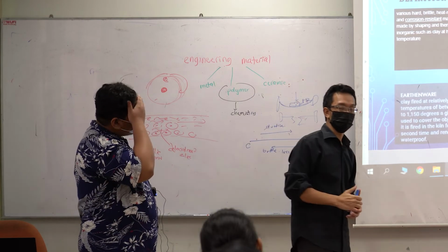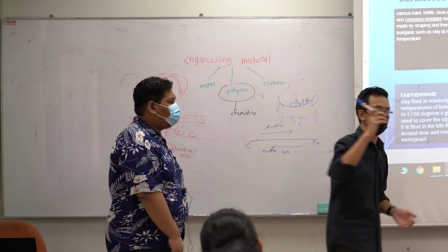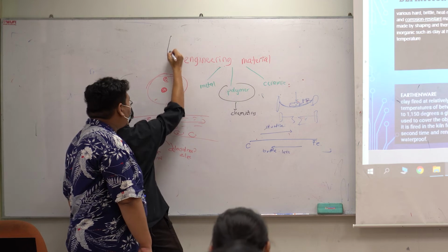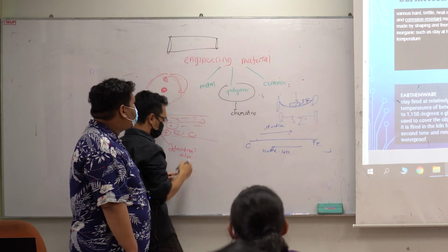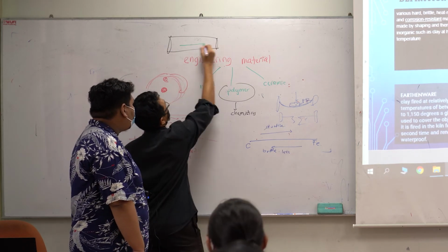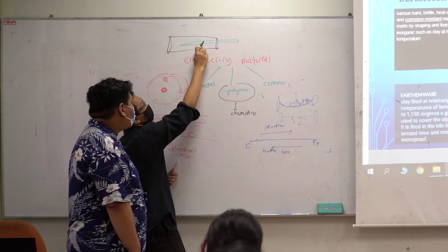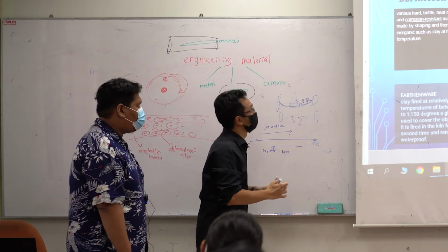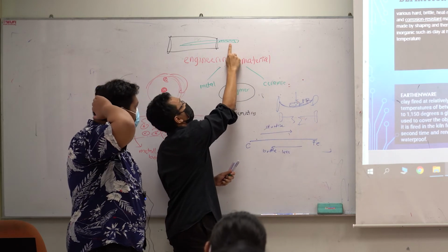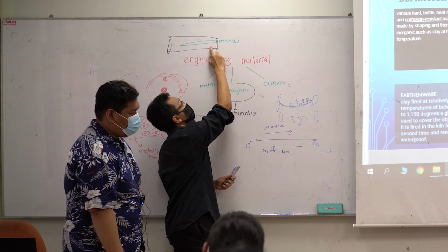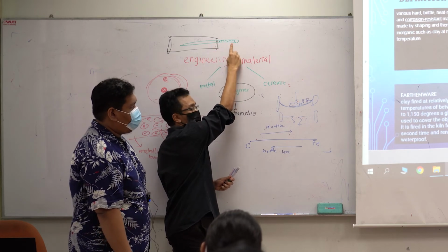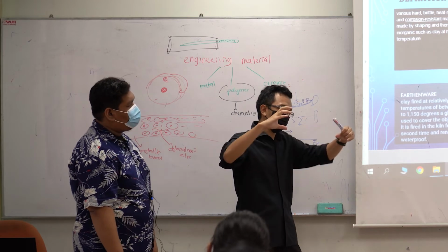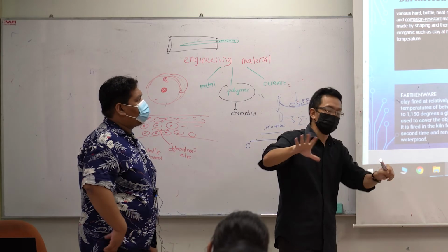Concrete. That's why concrete is a ceramic, but the structure that you see normally is the concrete plus something. The structure that you see is the concrete, and then inside the concrete they put something. They put metal, right? That's why in any construction they have the concrete, and then in the middle there is metal, the steel bars. Because they want to utilize the ductility of this, and to mitigate the brittleness of the ceramic, which is the concrete here. If they don't put this, then if there is any calamity, the bridge or whatever road will sort of snap just like that without any warning.